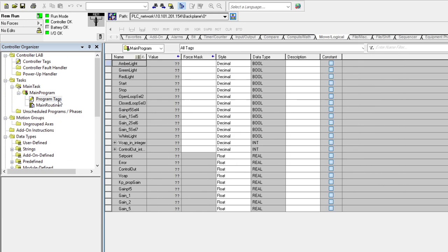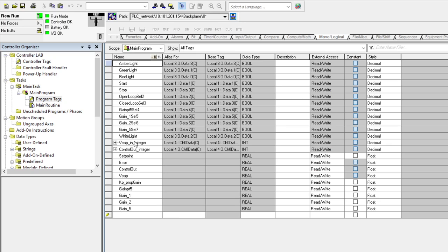So when we come back and look at the tags, we see that channel 0 input, I for input, is going to be in millivolts. That's going to be the voltage across the capacitor in millivolts. And then we're going to have the voltage out, which was our control signal out, which will also be in millivolts. Those are the actual outputs.